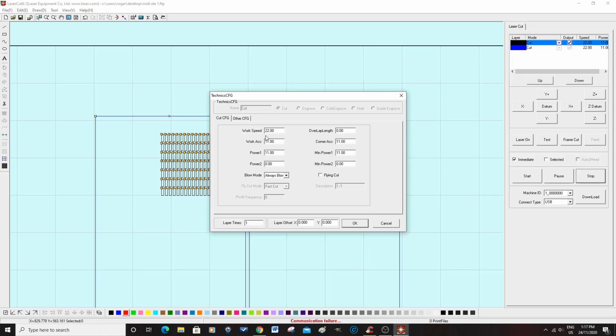Now we are cutting in 1/4 inch plastic or acrylic plastic, which is really the only type of plastic you should have in your laser. Because what a laser does is when the laser hits the material, it evaporates it into a gas. And you should have an active carbon filter and a good filtration system, because you can poison yourself, or long term it is possible to cause cancer.